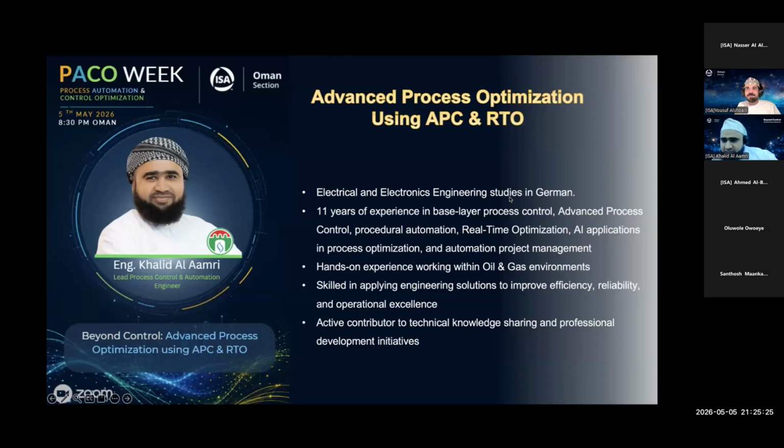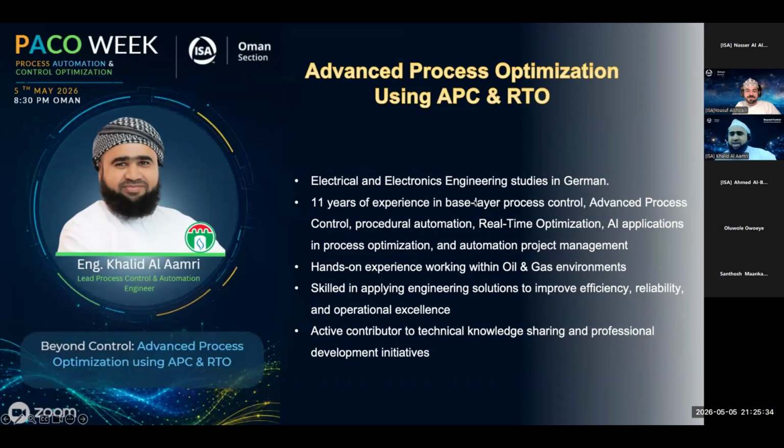Do we need to update the model frequently to match the physical process? Is there any way to do it automatically without human intervention? I think I did answer this. Even RTO has its limitation, because imagine a heat exchanger. With time, you'll have fouling. So the process engineer would tell you the UA has to be updated because it's not as efficient, it's like having fewer tubes.